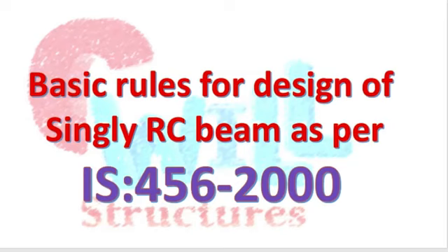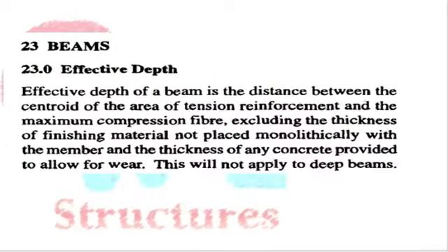RC beam as per IS 456:2000. As per clause number 23, how to calculate effective depth? Effective depth of the beam is the distance between the center of the area of tension reinforcement and the maximum